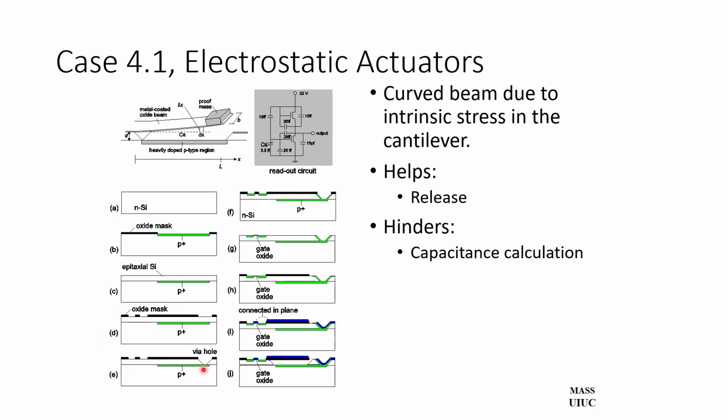Part of the oxide forms an opening window that allows anisotropic etching to happen to open up the underlying high conductance region. The other two windows on oxide are used to dope with a source and drain so that you can integrate electronics with some MEMS monolithically. You grow a layer of gate oxide and use the common process to grow MOS transistors.